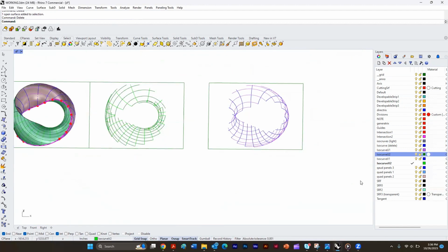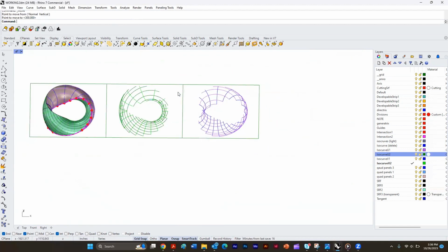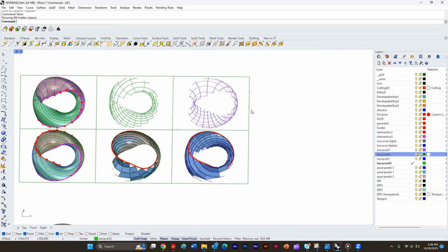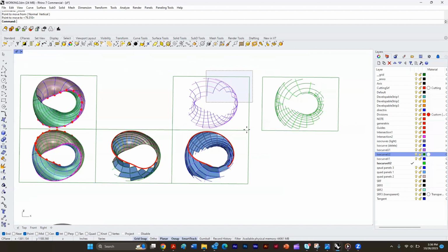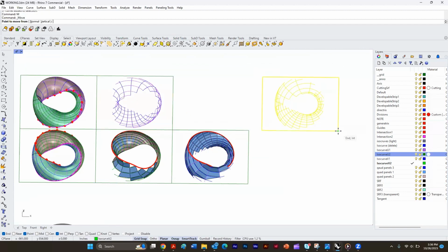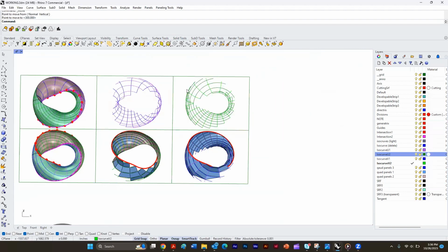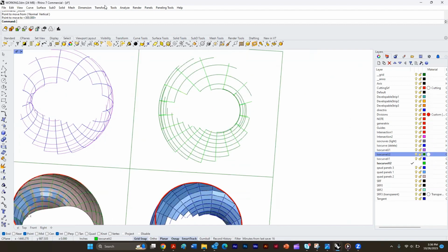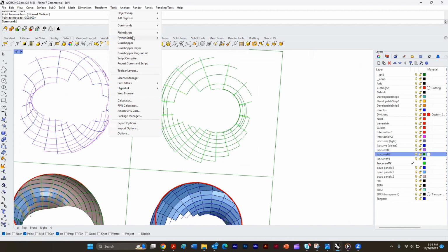And I can panelize these, which if you look, I aligned them backwards here. Let's align them correctly. That one would go there. This one would go here. So this is the same surface again, but it has a different set of isocurves. So let's just panelize that.